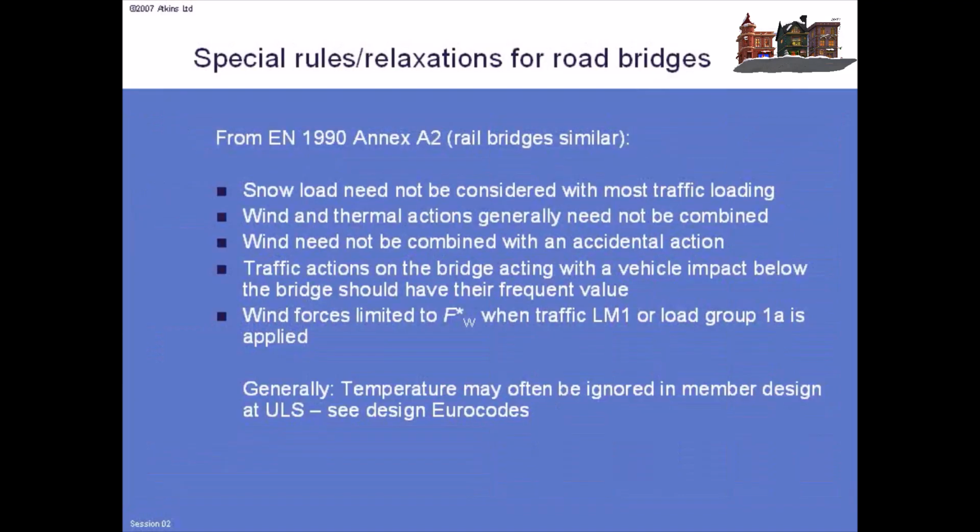These are the exceptions I mentioned about not having to combine everything together. So the exceptions are given in Eurocode in Annex A2. And so we get things like snow needn't be considered with traffic loading, wind and thermal needn't be combined together, wind need not be combined with an accidental action. There was some argument about that, particularly when you come to ship impact.